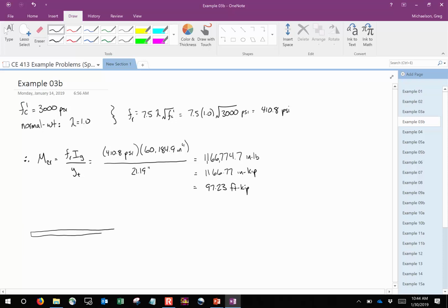Now, based off that last homework that you all just did, you should probably be able to tell me that if you have a simply supported beam with a length of L, what is M max? It's not wL squared over 2, it's over 8, right? Now, did anybody look at that guide that I posted? It was in the design aids and supplements. Did anybody look at that? Here, we got time. Or if I can pull that up.